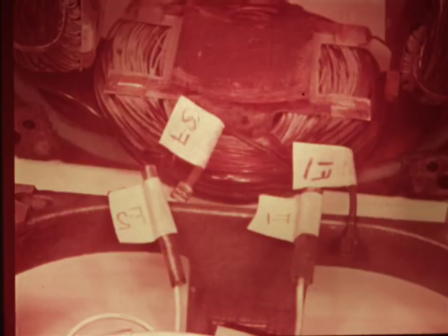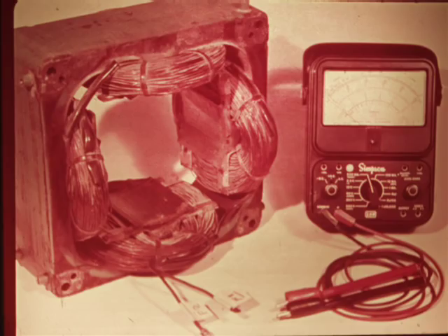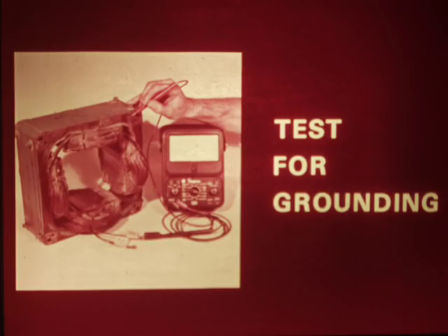Now, disconnect the field leads from the rectifier in the housing. Be sure to mark the leads and terminals for identification. If they're crossed at assembly, the generator won't work. Test the field for grounded or open windings. Use the same ohmmeter or powered test light. Check from each lead to the field case for grounding. There should be infinite resistance, no continuity, or the field must be replaced.